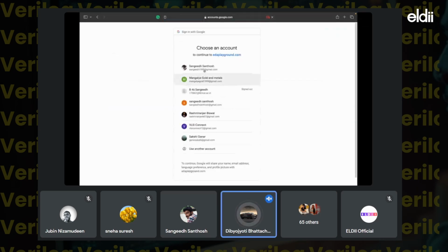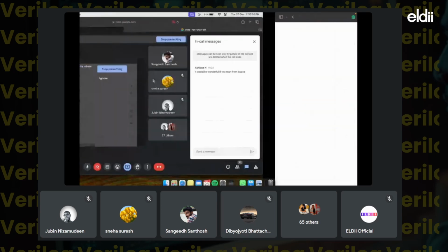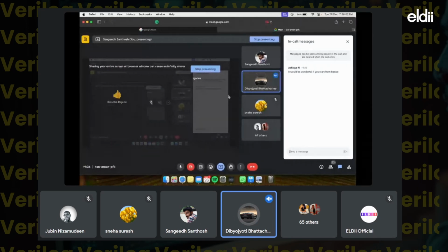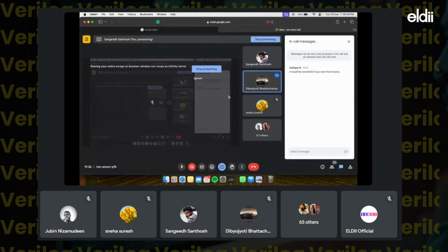Yes, sir, I have a question. Regarding that dump file or dump vars, I didn't understand the specific code. What does it do? The thing is, in the dump file we have written dump.vcd in inverted commas. After executing that code, there will be a VCD file. In that, various variables will be there, and how the values vary will be written.